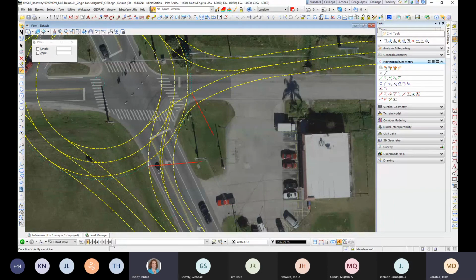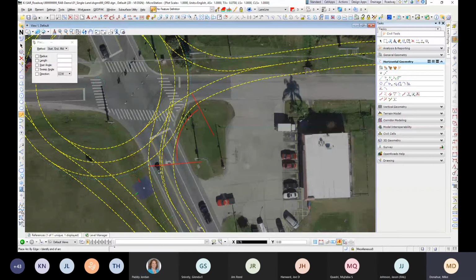And then this area in between, this odd little area, would also be a surface, which would require me from here to run an edge template or a linear template to complete that edge condition. Unless I'm doing something weird, like if I have my sidewalk coming way out here to cross, I may just run a template for my curb and then detail model my back and front of sidewalk points, triangulate that, give it depth, and then just fill in the void with another triangulated surface for sod.